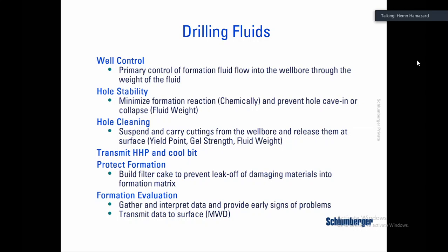Of course, the mud you pump from the surface is at normal temperature, it goes down, and it cools down your downhole fluid, especially the bit, because at the bit you are applying a lot of weight and torque, and the rock, for some types of lithologies like anhydrite, for example, is so hard, it's even harder than cement.